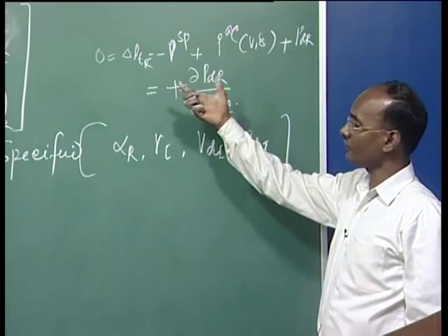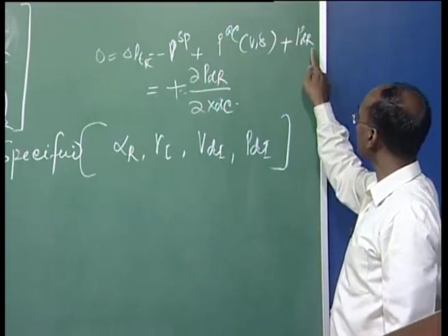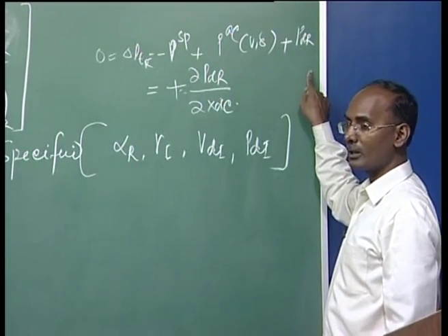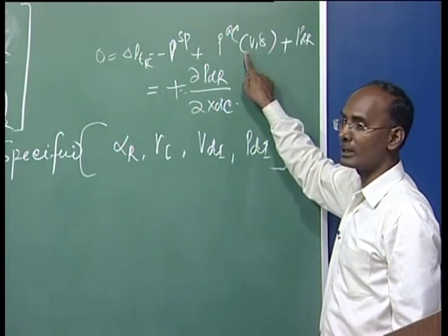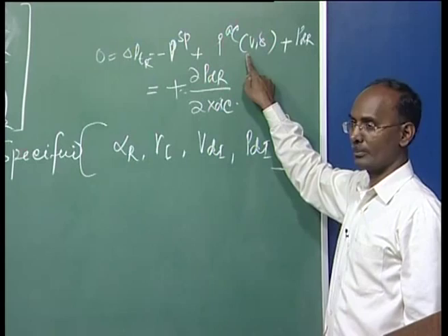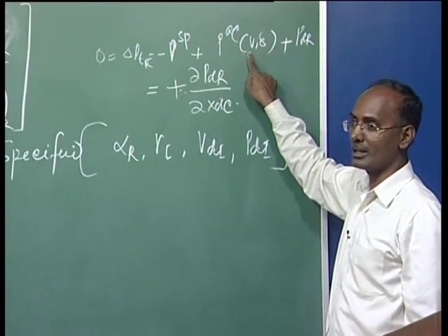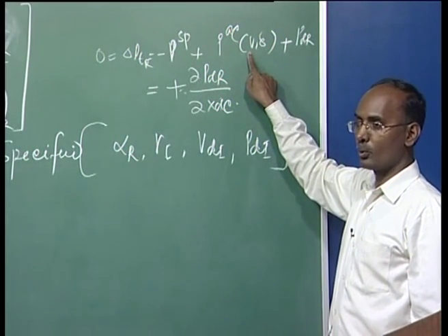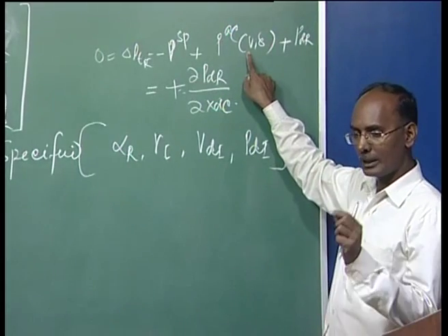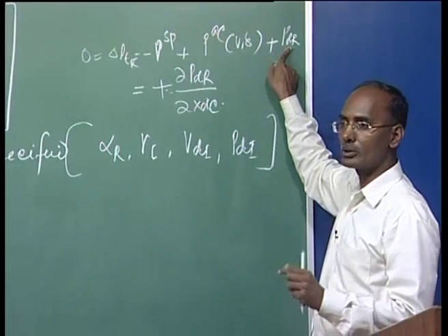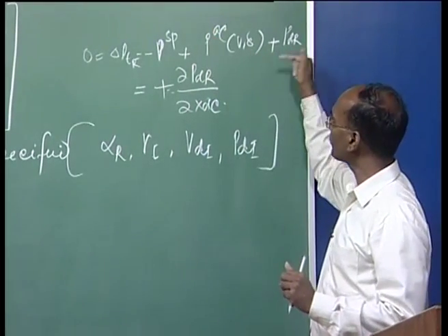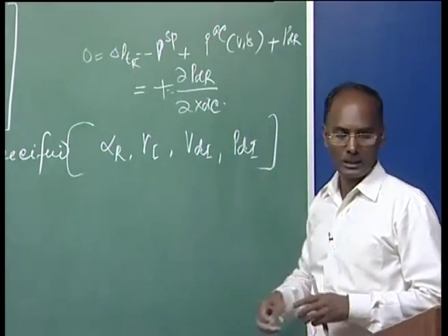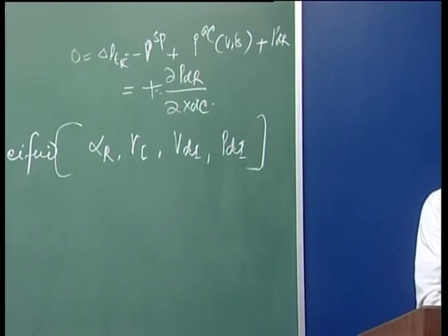Once you differentiate with reference to VTI and VTR, for others it will not change, but for VTR and VTI this term is going to be added in this Jacobian term, because this also has VTR and VTI. So, only at the 2 points, the rectifier and inverter, this term is going to be added. This will only come when you differentiate with VTR and VTI.